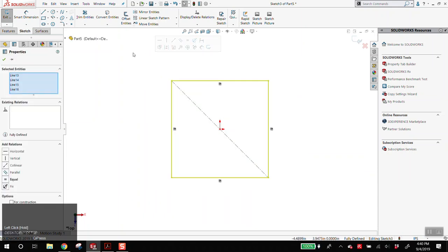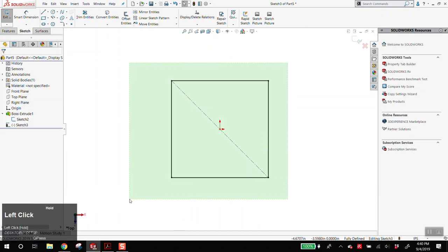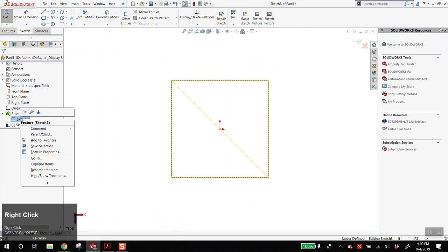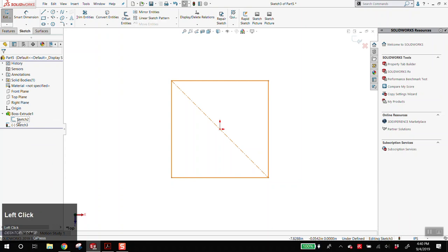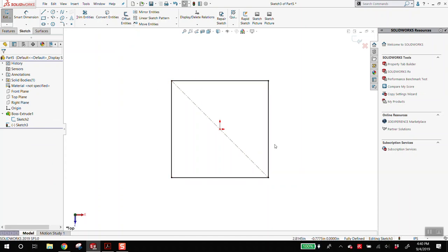And this can be useful to offset the hole that we want in here. So again, I don't know if I'm going too fast, but if you need to see a sketch in another feature, right-click, click on the eyeball. If you want to copy the sketch, you can click on it and hit Convert Entities or hit the hotkey C for Convert. And now you'll notice that I have this black box in here in my new sketch. It's black because it is literally copying the box from the previous one. It's aligned with it. It's defined by it. You'll notice, what line did it not copy?